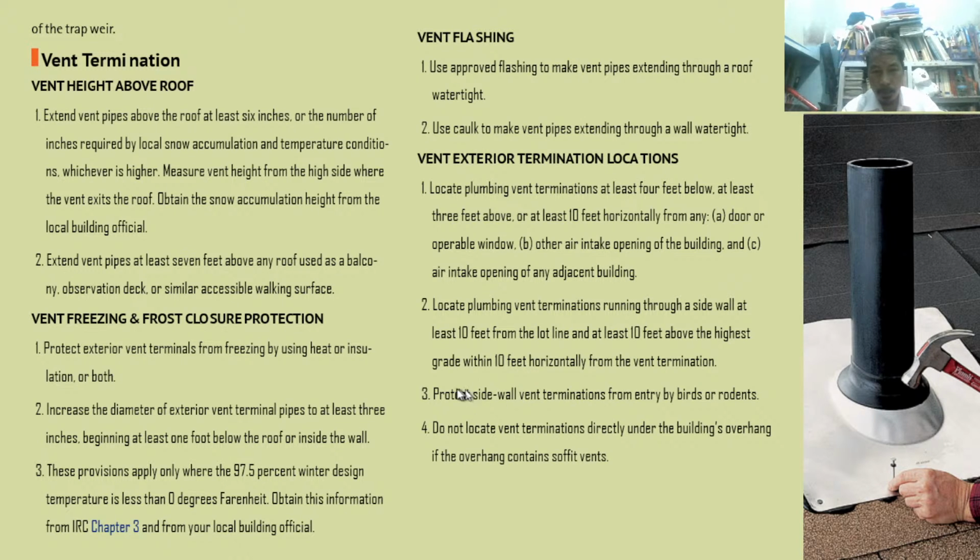Okay. And protect sidewall vent termination from entry by birds or rodents. Okay. Usually, birds and rodents may die inside this vent. Okay. Do not locate vent termination directly under a building's overhang.